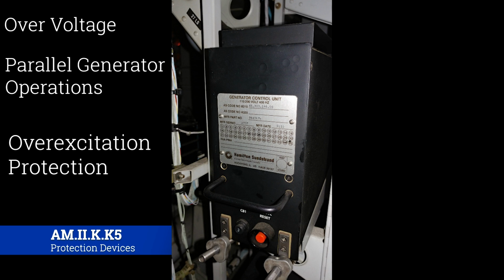Well, a generator will burn out. It'll catch on fire and do any number of things. So if you have one generator that basically just quits for whatever reason, just a hard failure, and you don't have overexcitation protection built into your overall architecture, then that second generator is going to simply start producing more and more power, and eventually it'll just burn up and cause a fire.